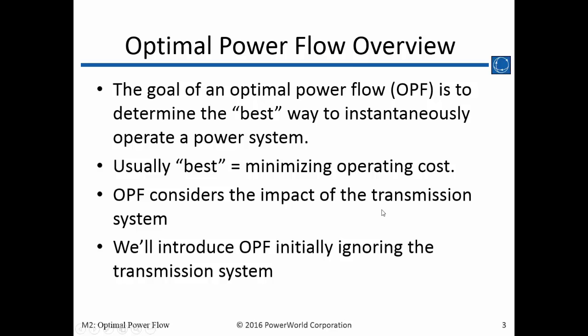With the software itself, you can configure it to ignore the transmission system or to consider it. In considering it, you can ignore certain limits if you want, either through the limit monitoring settings or through various OPF settings. You can tell it to ignore certain classes of constraints, like all interfaces or all transmission lines, and you can also do it on an area by area basis.